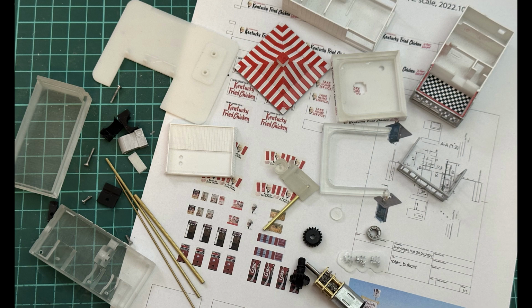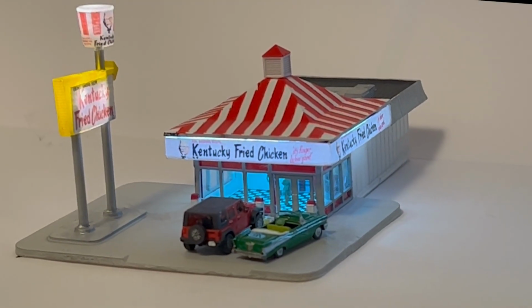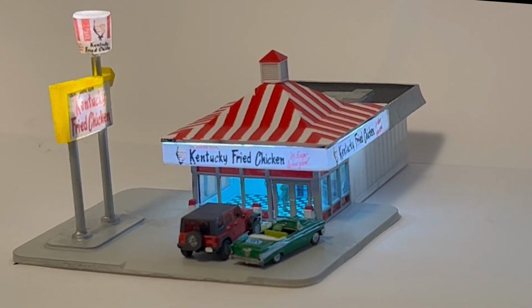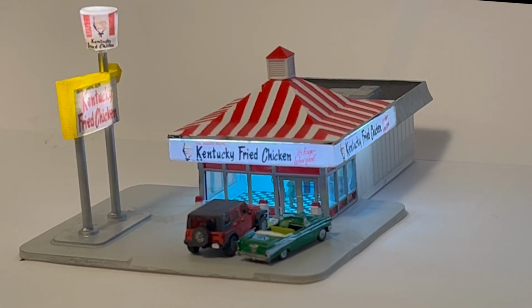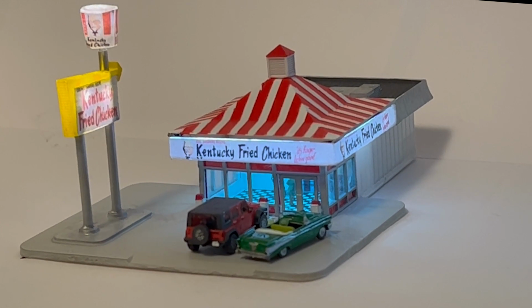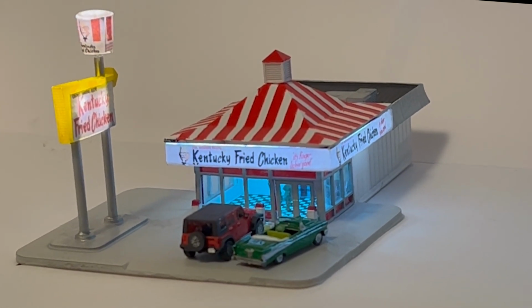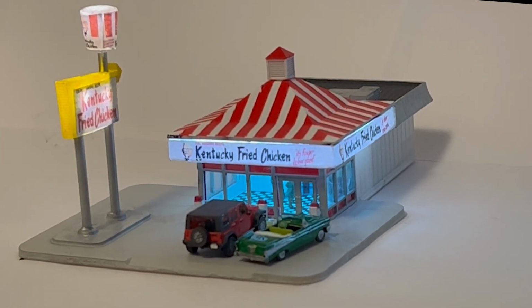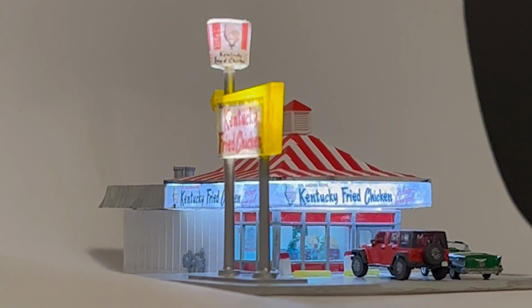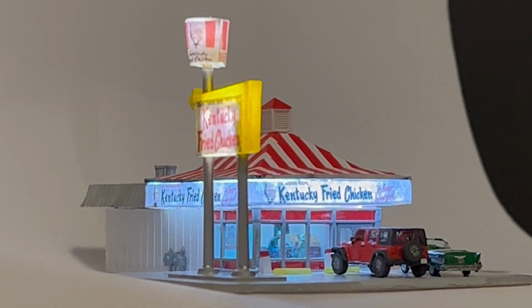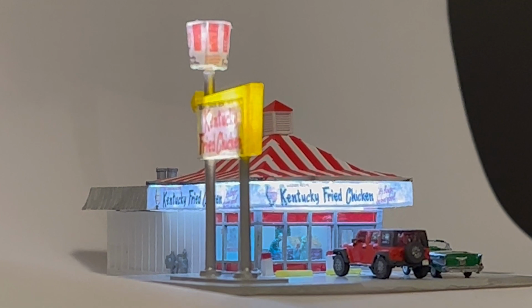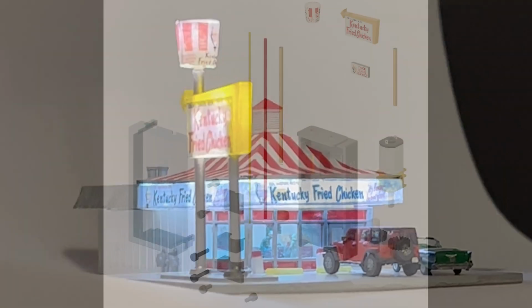The rotating bucket is driven by a motor and a gear mechanism, running at a very low speed. There was a problem to solve: the bucket should rotate, but the LED inside the bucket should stand still and not rotate. The solution was to use 3 different tubes. The tube holding the bucket is constructed using 3 different tubes, mounted inside each other, a 1mm tube, a 1.5mm tube, and a 2mm tube.